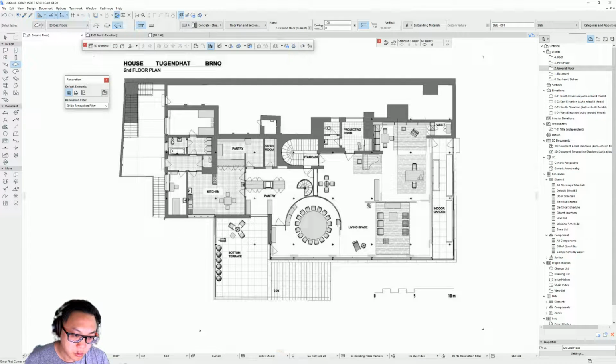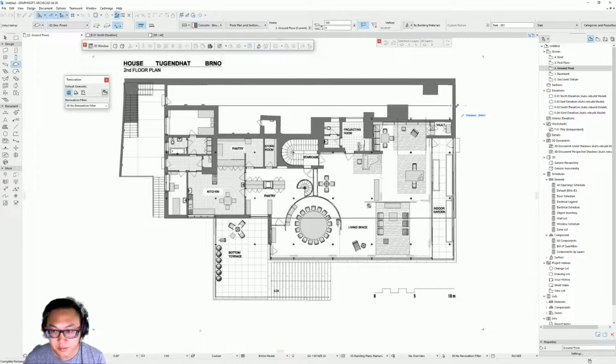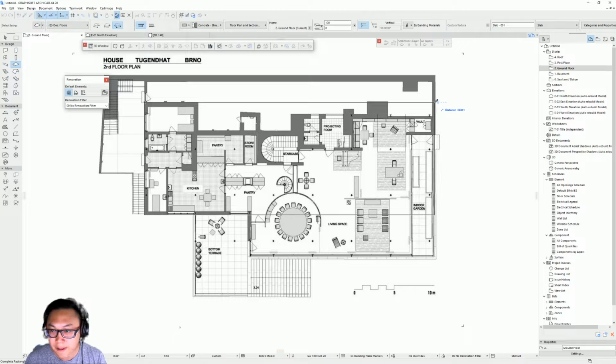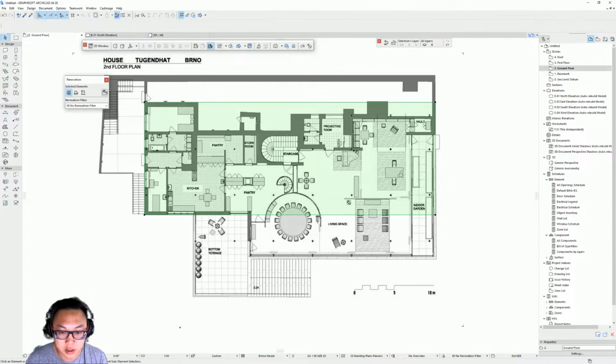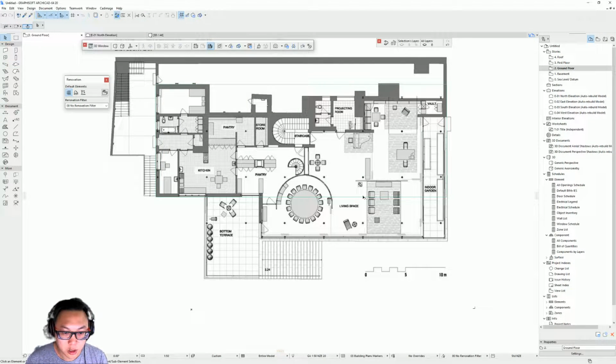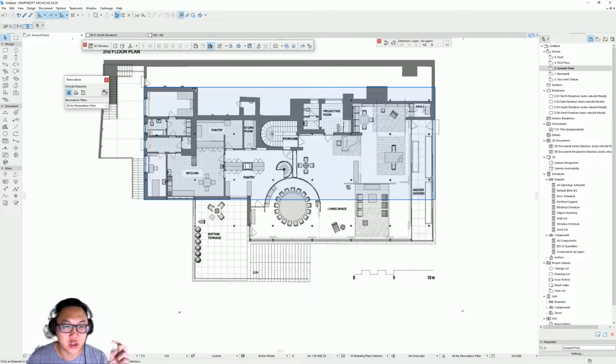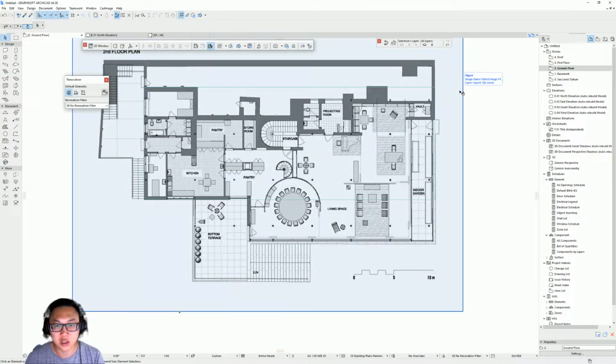So I'm going to start here, and I'm just going to try to round things up. So 30 and 45, and as you can see, because I've selected the geometry methods, there's either the rotated rectangle, where you draw one edge first and then you can just pull it out here. For this I'm just going to use that, and 36,500. Okay, so I got this slab here. Usually I tend to do that to make sure that everything is squared.